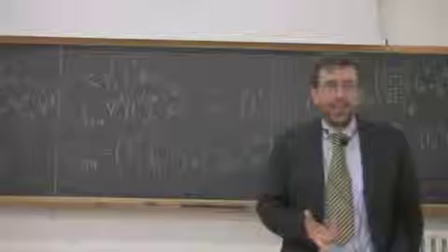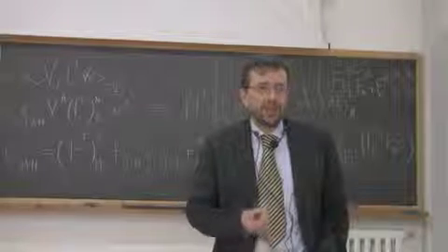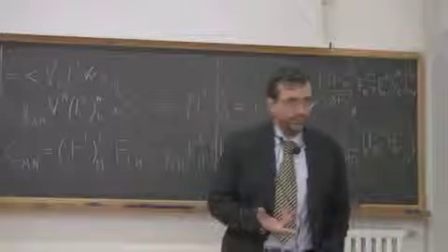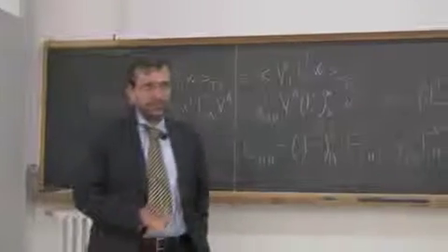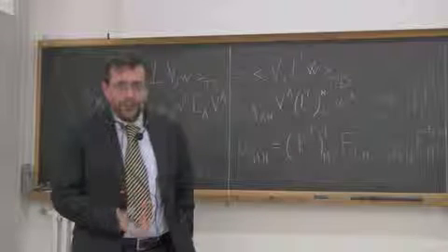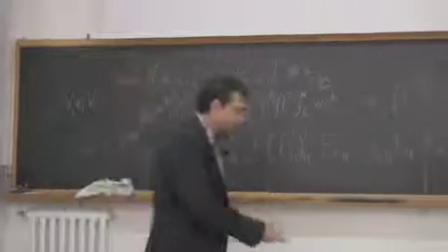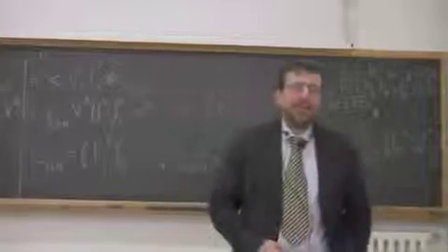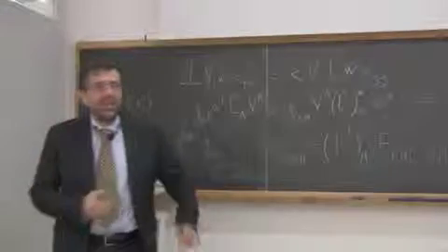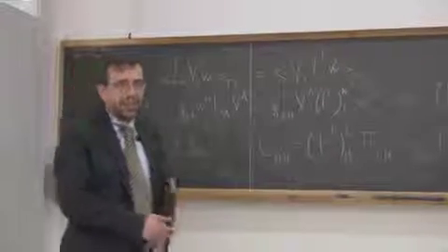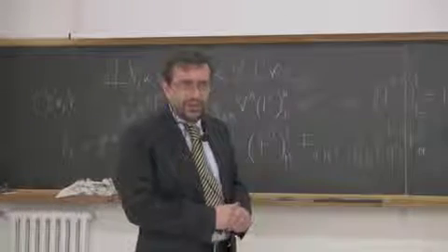in an easy way the invariance of deformation energy under change of observer. So if you have a body which is being deformed, and if you consider 2 observers which measure what is happening to this body, it is obvious to state that the deformation energy needed to place your body in a given deformed shape is independent of the observer.